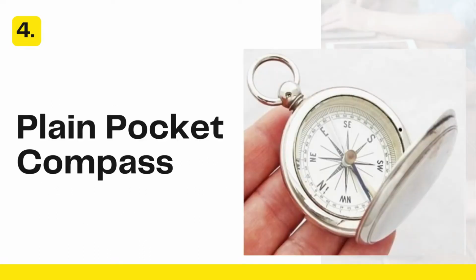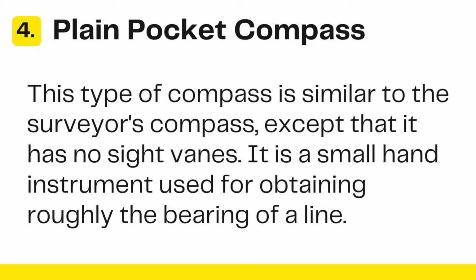And the plain pocket compass. The plain pocket compass is a type of compass that is the same as a surveyor's compass, except that it has no sight vanes. It is a small hand instrument used for obtaining roughly the bearing of a line. Various pocket compasses are used in reconnaissance and exploratory surveys.